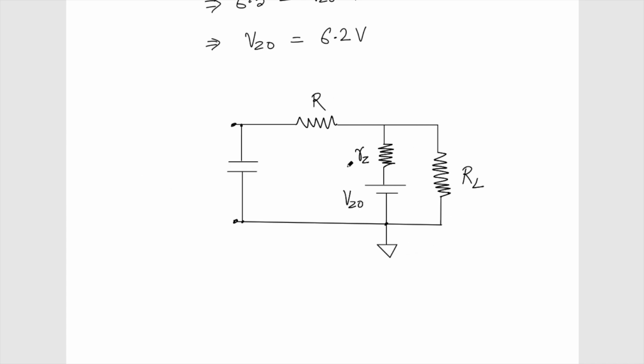Okay, so this is the model, this is my R, this is the model of the Zener diode, and of course this is the load resistance. And if you see the waveform that is applied here, the rectified waveform after filtering, the Vrect will look something like this, supposed to be plain DC, and this is my Vout. It will have a maximum voltage, let's say maybe 10 volt.